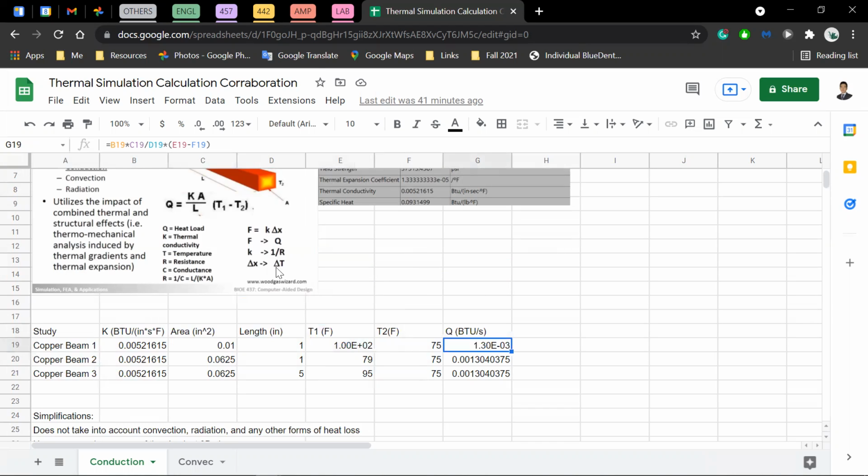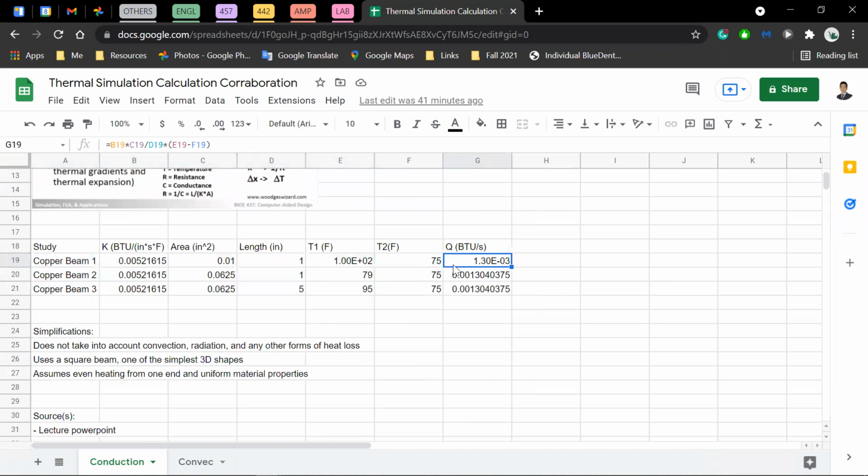All right. So the reason why I want to go over these calculations first is because we're going to actually use this heat load to see if we can replicate these 2 temperatures in the simulation. So to clarify, I chose these 2 temperature values to see if the calculated heat load when applied in the SolidWorks simulation can give us these 2 temperatures back.